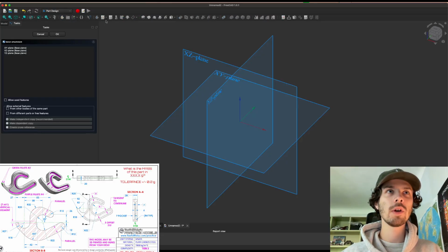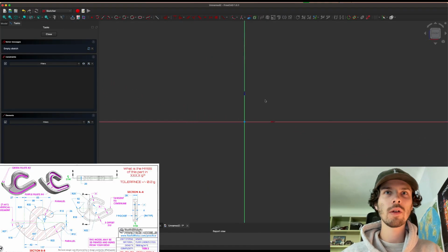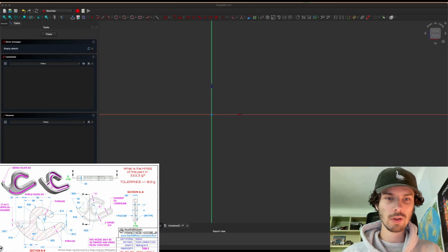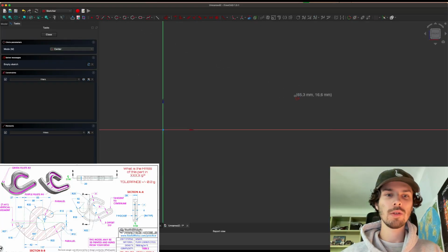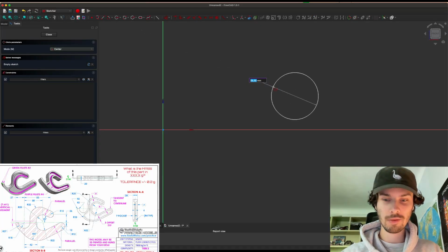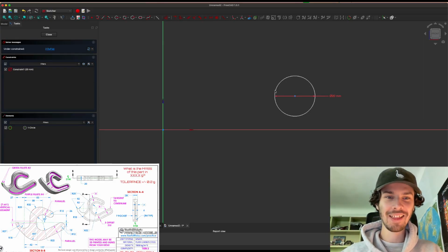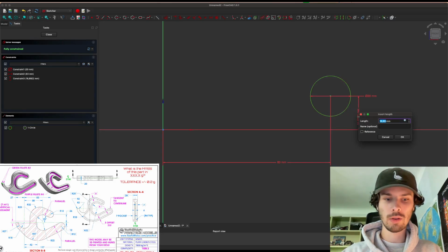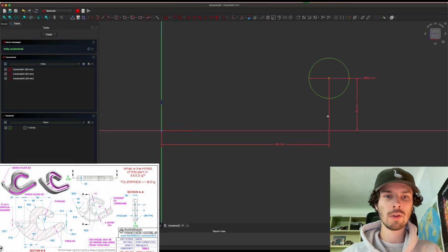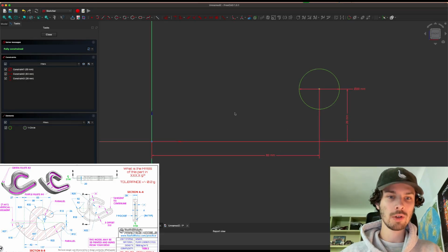So yeah, in FreeCAD, let's start a new plane, and let's start adding things. So the first piece that I'm gonna add is a cylinder, not cylinder, but a circle. Adding some dimensions to it. So this one's 83 millimeters, and it's about 26 height. 26, great. Moving on to the next shape.